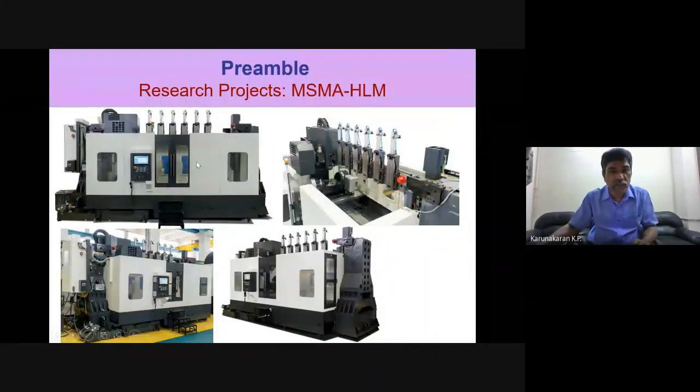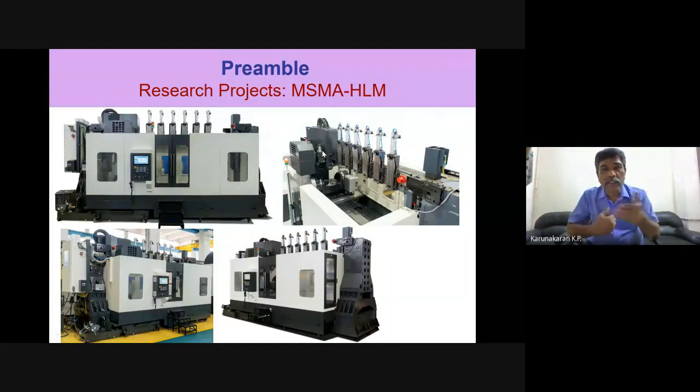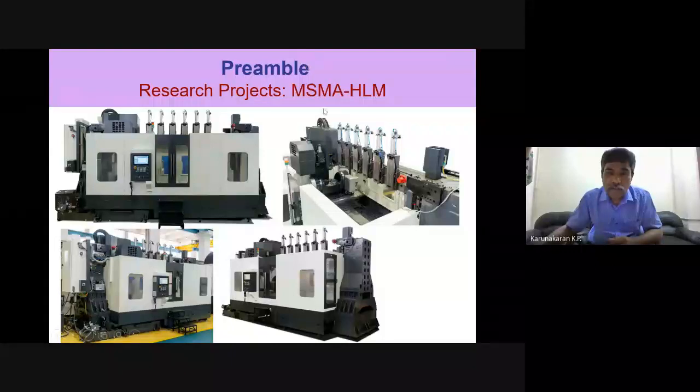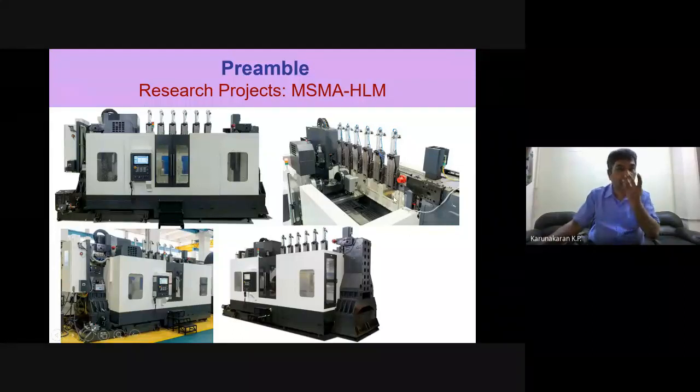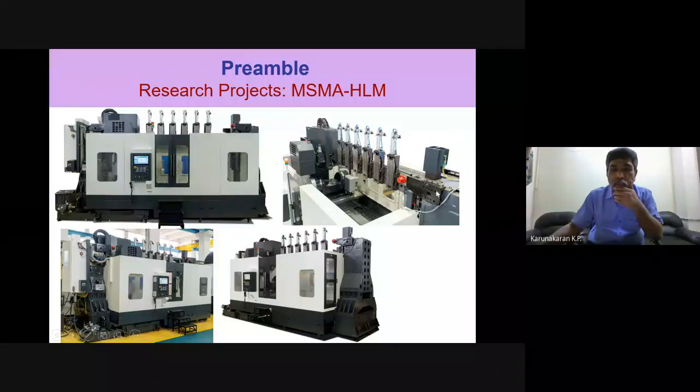So this is the front view of the machine. These are the two side views. You see this machine from the top view. The machine on this side has a VMC, vertical machining center. Basically, it's a pair of VMCs looking at each other, amne samne. Okay, so you have one VMC here and another VMC here. They look at each other, and you see the Z motor of these. They together lift a long beam.